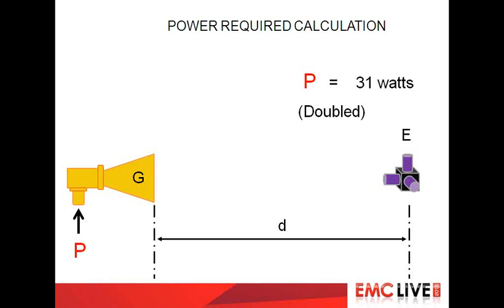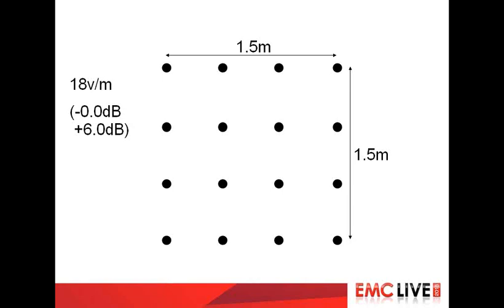So that break off there was basically to describe the impact of beam width, now that we're into high frequency testing. Now that we have narrower beam widths and higher gain, we need to take the beam width into account. So if we look again at our requirement, and bearing in mind we have the situation where we've defined our zone of interest and discount anything either side of it, it would be nice to also define our degree of freedom in terms of the allowed parameters, that is, we cannot exceed +6 dB.